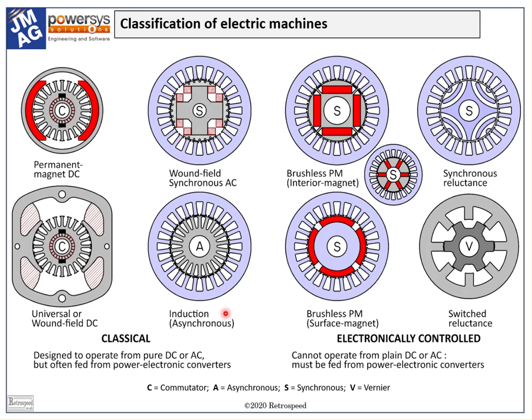Field-oriented control for induction motors was new and untested, and inverters were cumbersome and not as reliable as they are today. Brushless PM motors were mostly running with square wave 120-degree inverters, which seems crude by modern standards of sinusoidal drives. The race had only just begun.